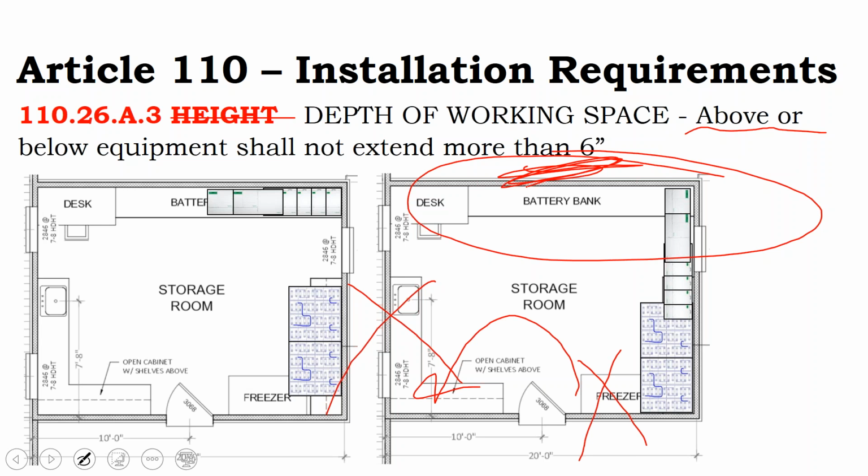And so if we wanted to have our battery bank and it's sticking out 3.5 feet from the wall, and then we say, okay, well, we want to put our inverters and stuff right next to it. Okay, well, we got 9 inches here and it sticks out 39 inches. So we can have kind of our 30-degree working space. Let's not worry so much about that.